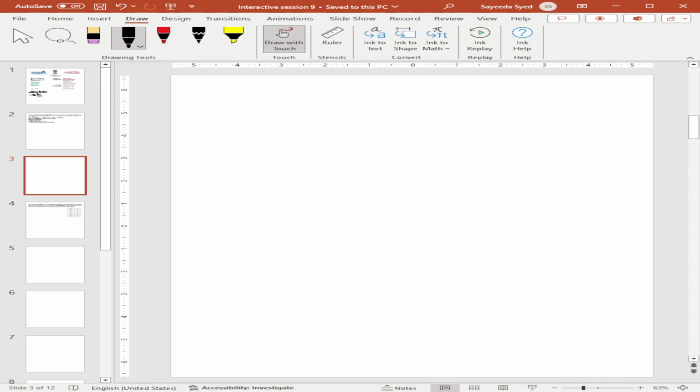Obviously there are some conditions in which shallow foundations do not work, and we require pile foundations. It may be when one or more of the upper soil layers are highly compressible and too weak to support the load transmitted by the superstructure.